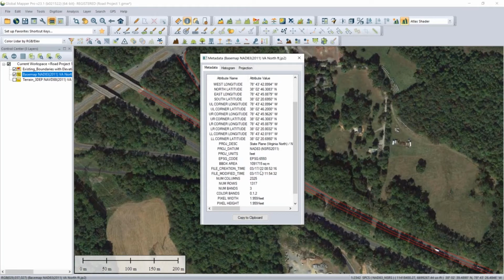The created date, now this doesn't necessarily reflect when it was flown, but this is a reflection of when the data was actually captured. I downloaded some data. If we were using a source of data online, we could go right to the source and we could get some information. Is this current? Was this data collected within an appropriate time frame? Also important in the metadata, we noted resolution. This is fairly high resolution. It's 1.9 feet, almost 2 feet resolution. So this is going to give us a reasonable amount of quality in terms of making decisions based on what we see from our imagery.